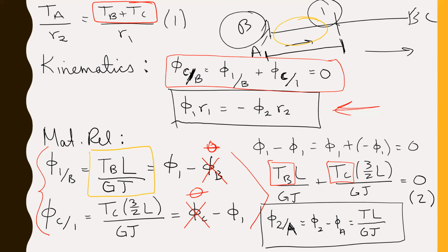That's looking at the rotation that occurs from point B to point C. What you're really calculating is the rotation of point C minus the rotation of point B. And in this case, it consists of two different things added together because there's an intermediary point that changes the behavior of the two sides. And it's really convenient when something is held fixed because then that value defaults to 0.